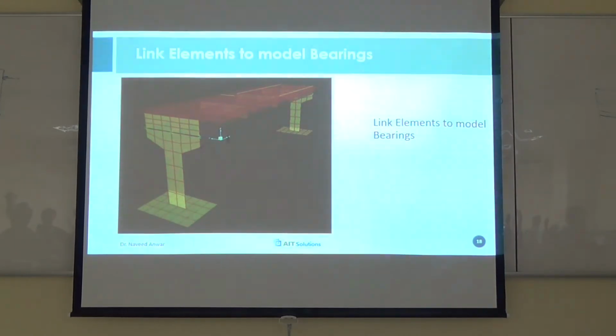For example, I've seen many engineers do that. They get a lot of torsion or bending moment that they cannot handle. They assume a pin or release the moment over there to solve their problem, but they do not construct accordingly. They do not stop the reinforcement. They do not make the link at the site. So the site is still behaving connected, but just to solve their problem, they assumed a pin over there. But they did not construct the pin at the site, so it doesn't matter.